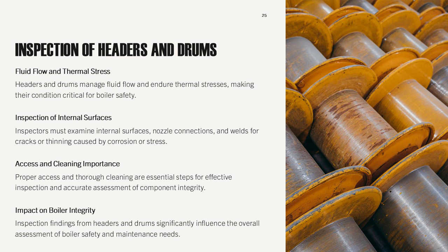Headers and drums distribute fluid flow and are subject to thermal stresses and corrosion. Inspectors should evaluate internal surfaces, nozzle connections, and welds for signs of cracking or thinning. Proper access and cleaning are essential for effective inspection. Findings from these components often influence overall boiler integrity assessments.